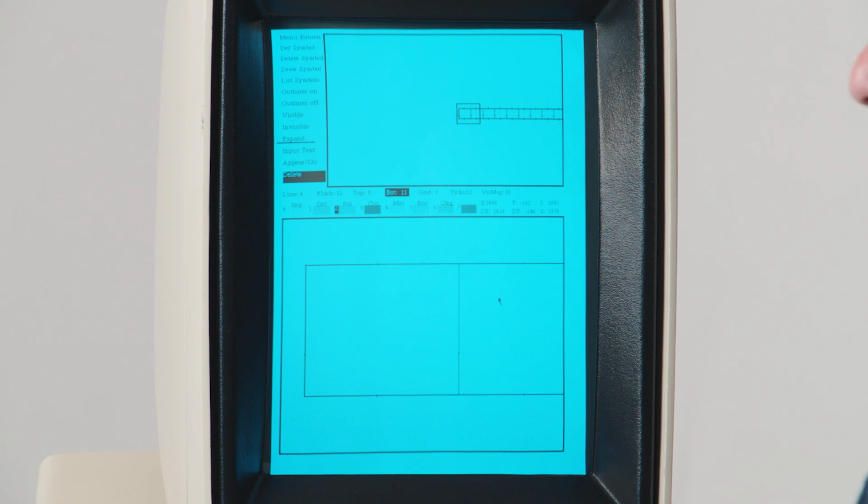Again, I know what's inside that cell. I don't need to see the details of it. And so it can draw it a lot faster and save memory by drawing it out this way. Now this is a good opportunity to show the advantage of working with 2 different windows. So I can click in the upper window. If I want to center the shift register, you can see there's 12 units or 12 bits of the shift register along here. Down here, I'm still looking at just 1 or part of 1, and you can see there's this rectangle which defines the portion of the upper window that you see in the lower one.